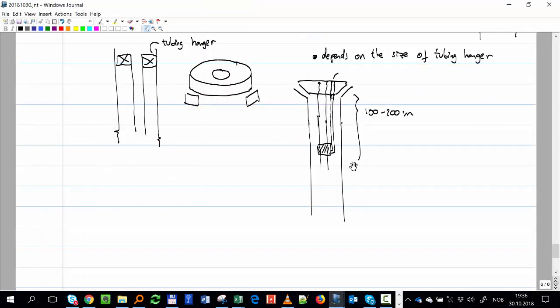So you have to pass all of this. The long story is that you have to make a hole in the tubing hanger to pass the hydraulic line. And you might have other things. For example, sometimes they put a pressure transducer socket at the bottom of the well, so they have to send another line for that as well. Sometimes you have a pump inside the well, so you have to make another hole. At the end, that hanger might have a bunch of holes, so you have to be careful that you don't have the whole space, but less than that.